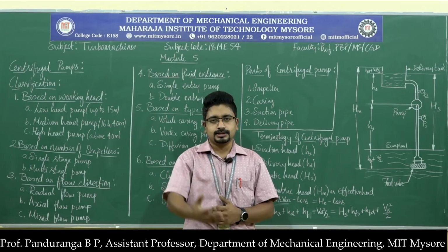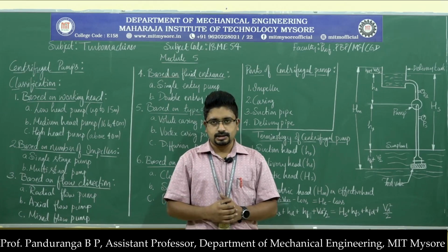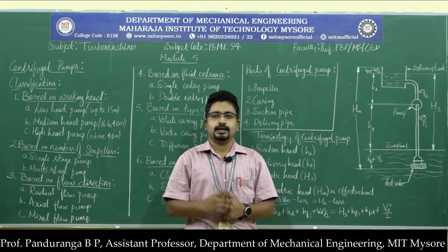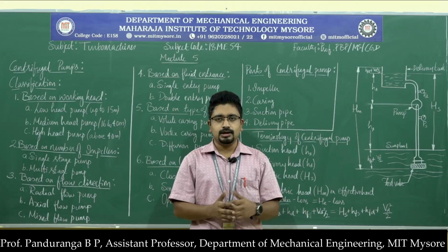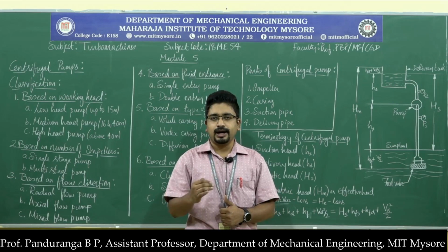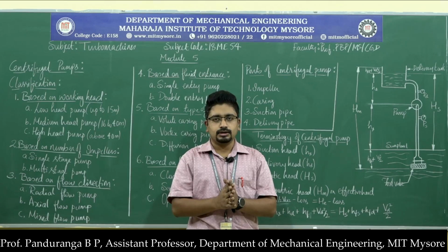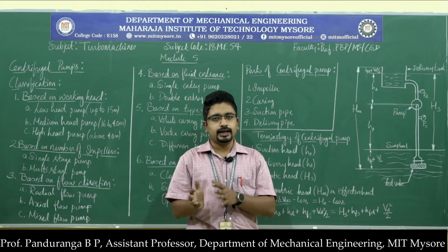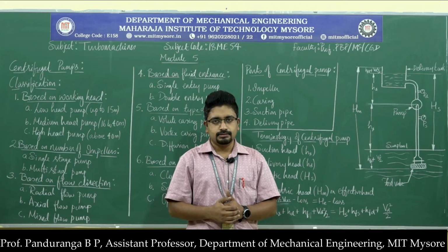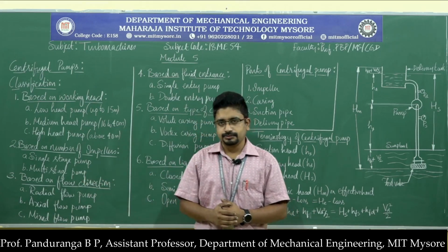We need a large discharge, and a single pump is not able to achieve that discharge for the given head. In that case, instead of using a single stage pump, we have multiple stages, maybe 2 or 3 stages of pump, where all the stages develop the same head, but they deliver equal quantity of water or liquid, thereby increasing the amount of liquid pumped through the pump. So that is where we go for multi-stage pump.